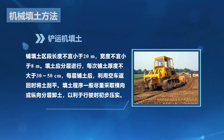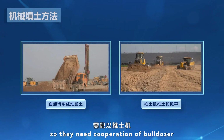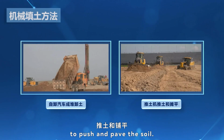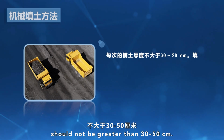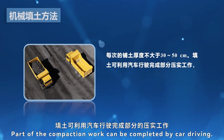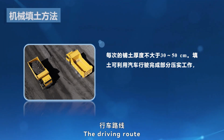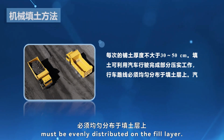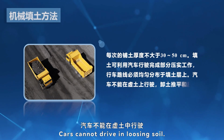During driving, dump trucks unload soil in pairs, so they need the cooperation of a bulldozer to push and pave the soil. The thickness of each paving soil should not be greater than 30 to 50 centimeters. Part of the compaction work can be completed by car driving. The driving route must be evenly distributed on the paved layer. Cars cannot drive on loose soil.